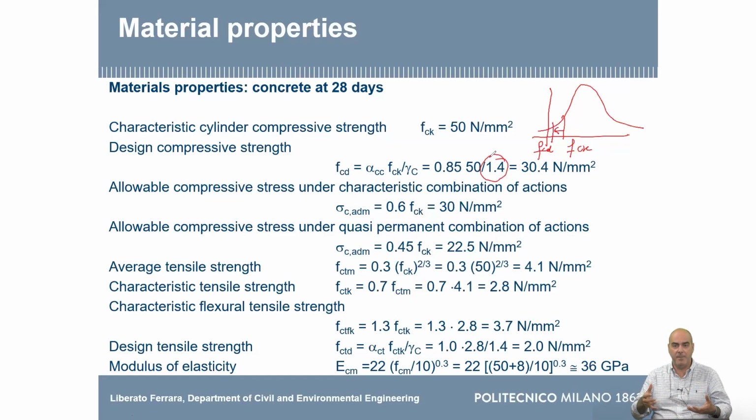First of all, because it's very heavy. The other thing is that if you go for higher strength concrete, you need a press with very high load capacity. That is the potential strength of the material. Then the material in the structure is something else. And most of all, there is a phenomenon called the size effect, based on fracture mechanics, which shows that the larger the size of your structural element, the lower its apparent strength in the structure. Well, let's say that for compression, this 0.85 factor also accounts for that.